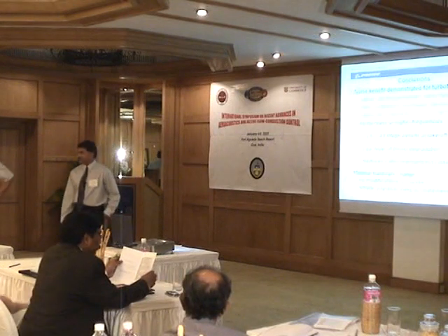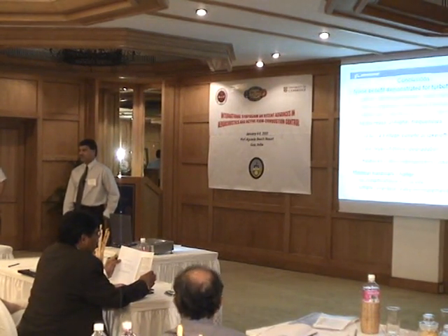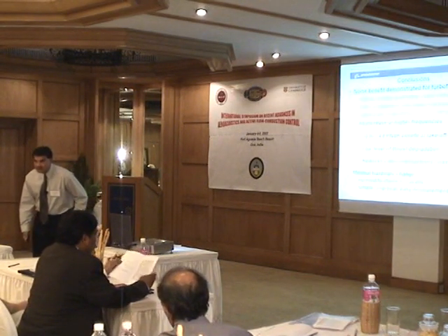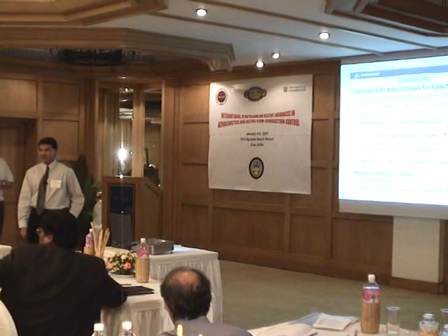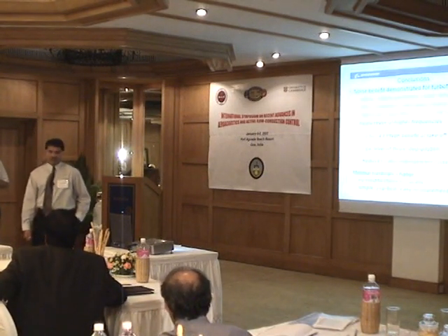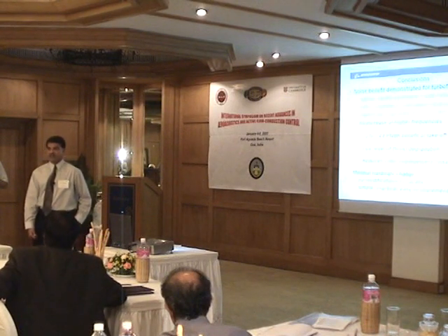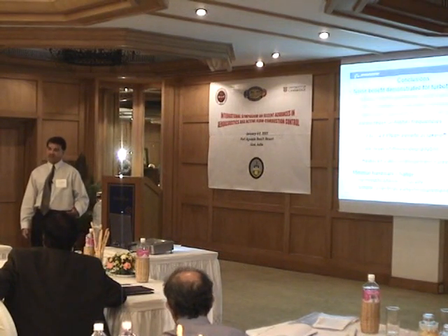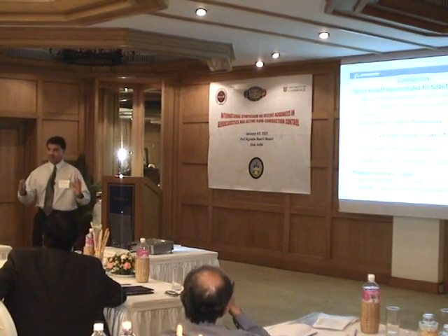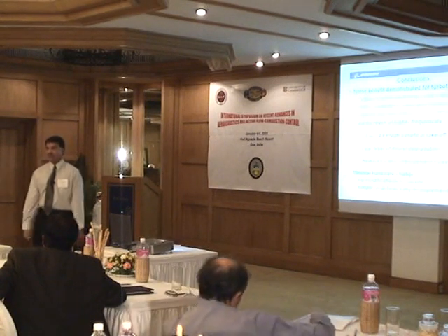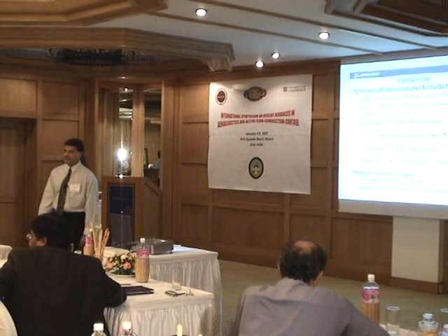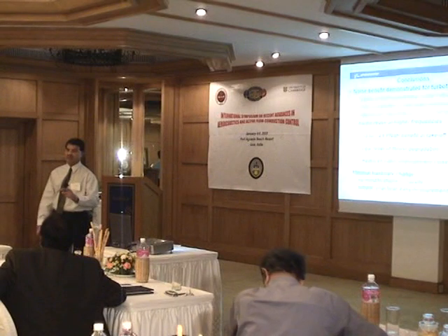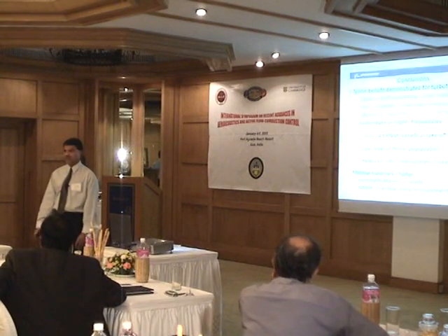In the interest of time, just one question. Would the thrust loss of 0.2% be accepted by the customers? I'm not saying we have to live with this. What I'm saying is, even if you just take a straight nozzle and cut it straight, you get 0.2%. But we can be cleverer than that and redesign the primary nozzle, the last portion of the nozzle I showed on that 747 engine, to reduce the thrust loss. If you can push it to below 0.1%, it cannot be measured. So if you are just within the error band, that will be the goal too.